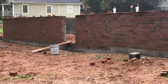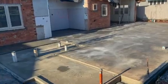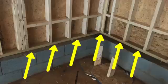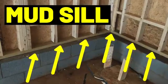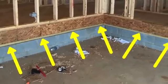Okay, let's get down to foundation level. Before framers show up, masons have either built up brick and block walls or poured concrete foundations. In either case, they give us a level base to build off of. In most houses, the first framing member we install is the mud sill or just the sill. This little known piece provides a stable layer for all the framing above it to rest on.